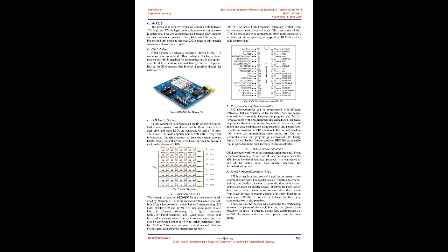For the microcontroller, the system is based on the PIC16F877A microcontroller developed by Microchip. It is an 8-bit microcontroller which has self-programming, 256 bytes of EEPROM and 40 MHz maximum speed. It also has 8 channels of analog to digital converter, A/D, 2 PWM functions and a synchronous serial port for serial communication. The synchronous serial port can also be configured for either 3-wire serial peripheral interface, SPI, or 2-wire inter-integrated circuit bus, and the addressable universal synchronous asynchronous receiver transmitter. Fig 3,